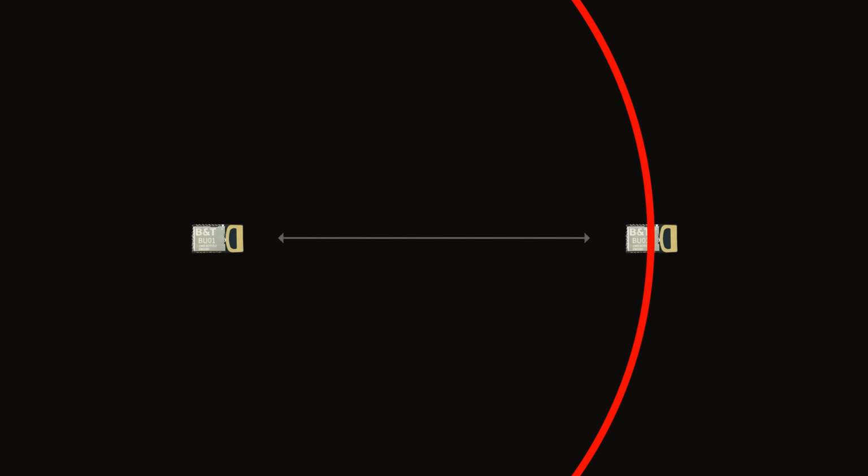Now, say we have 1 fixed radio. Let's call this an anchor. And we have 1 mobile radio with unknown coordinates. Let's call this one a tag. We have the distance between the 2, but no other information. That means that the tag has to exist on some point on a sphere around the anchor. And since 3D screens died out in the 2010s and we all have 2D screens, I'm going to have to make this a circle.